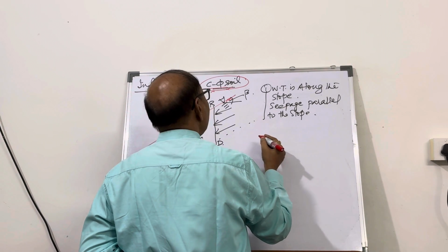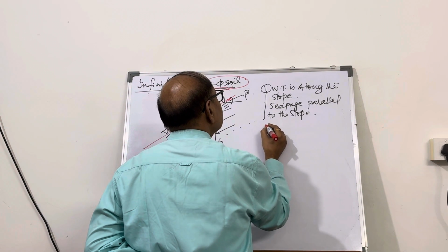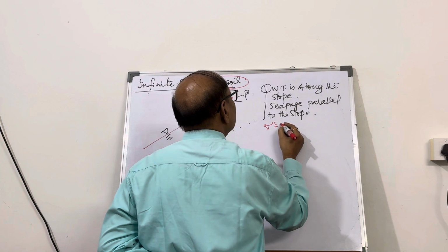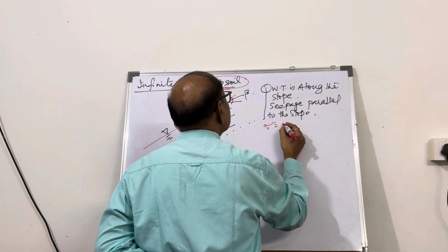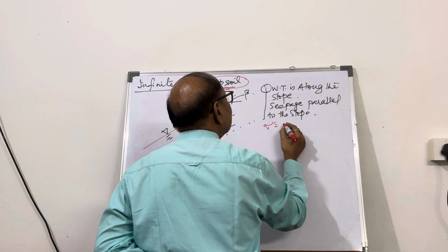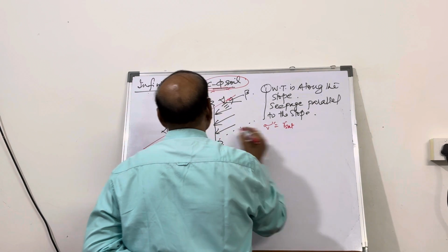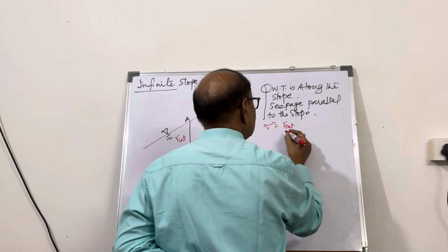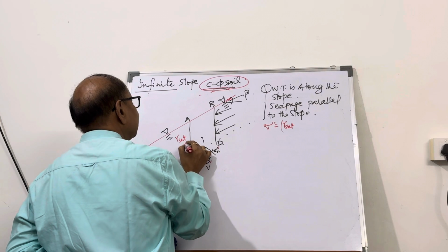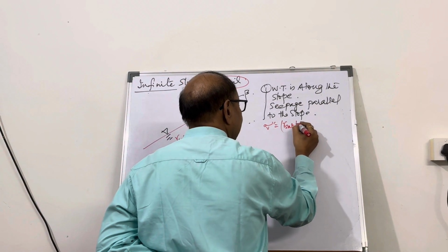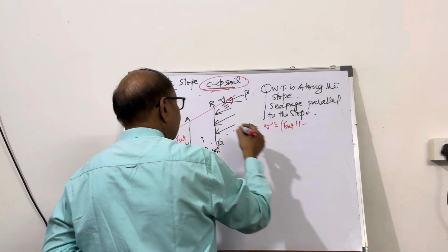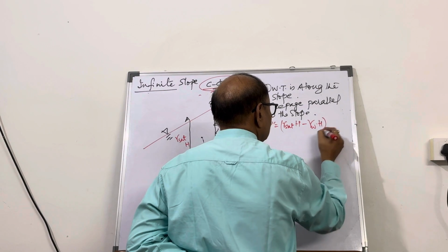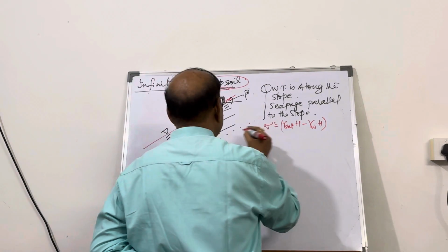So here, quite simple, you know it, the effective vertical stress will be how much? The water table is up to here. So gamma saturated, that is the unit weight of this slice, and let's say the height is h. So multiply it by h, minus, because the water table is there, the pore water pressure gamma w into h, must be directed into cos beta.